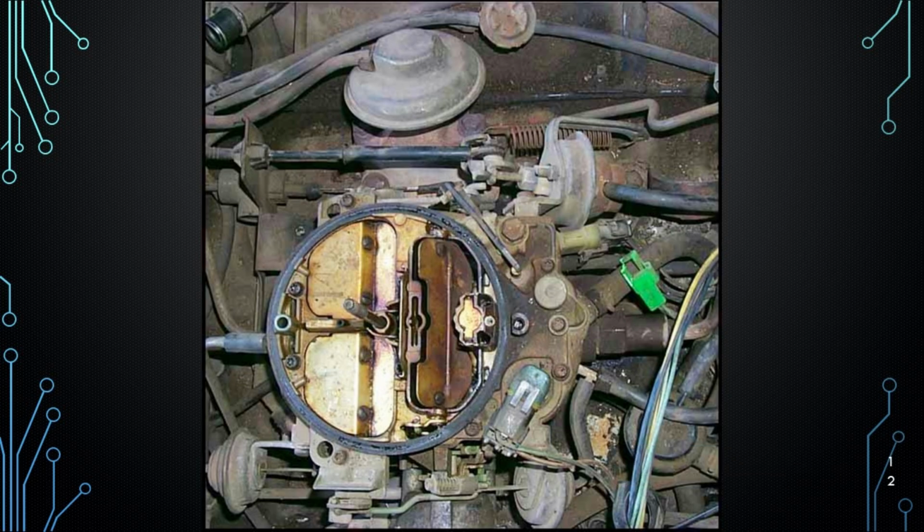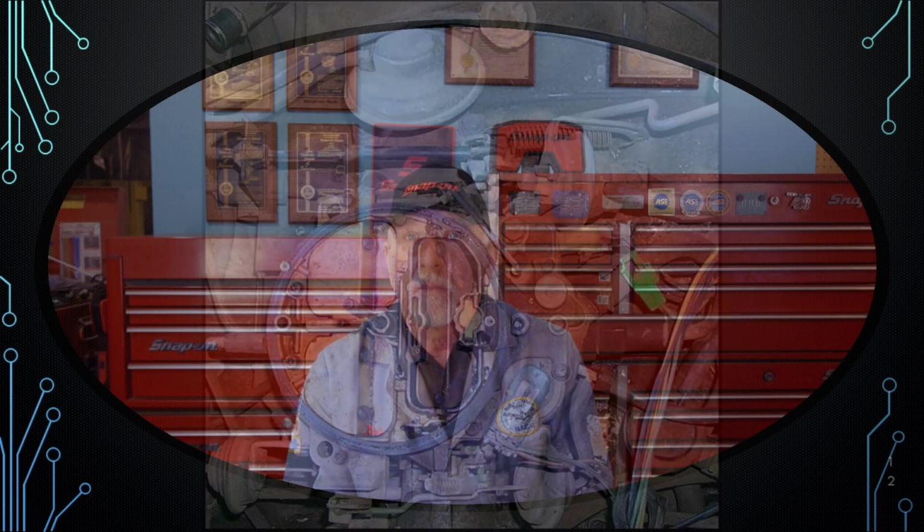Throttle position sensor wiring on a feedback carburetor typically comes from the side, near the throttle shaft. You'd usually see a harness or wires coming off the side of the carburetor, around the throttle linkage area. It won't be on top. Instead, you'll see it aligned with the throttle plate, sensing its rotation. In short, it's on the side, tracking throttle movement directly.